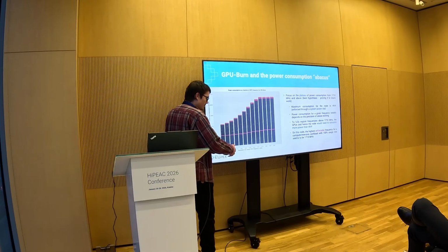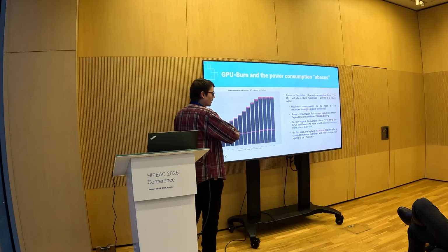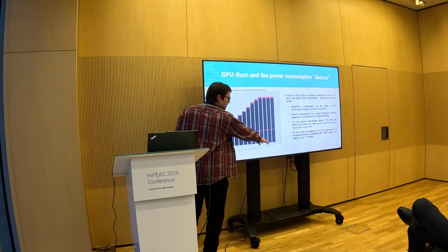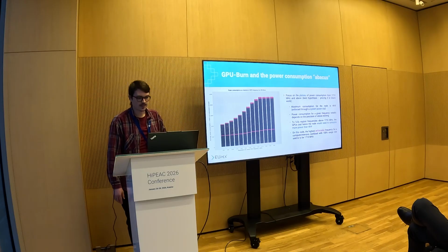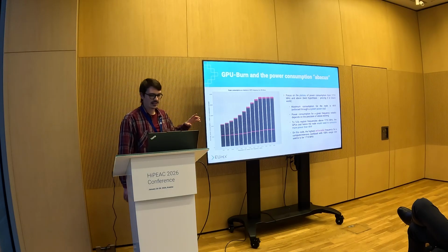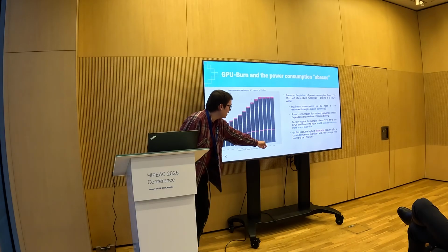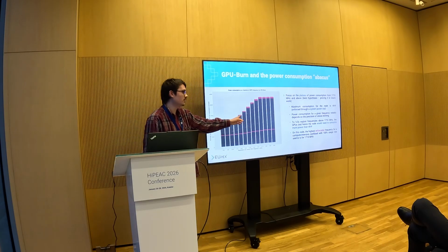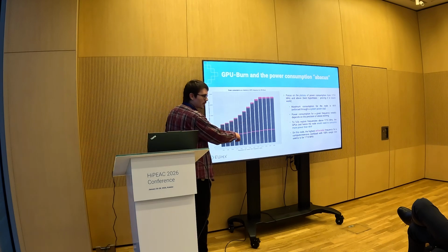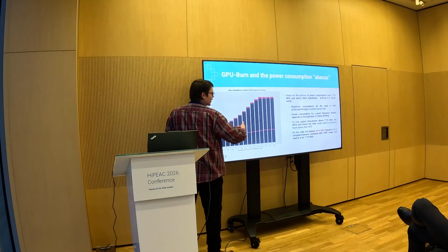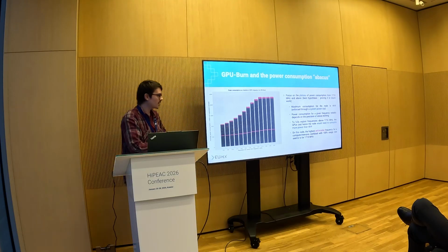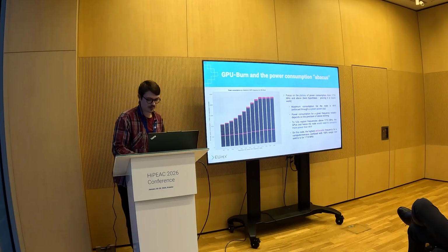So basically, it means that effectively, the node cannot sustain a higher frequency than 1710 MHz when fully loaded on this precise node. And something I want to have a few words about is that this value will depend on the specific node, because each GPU, depending on its etching, will not have the same power consumption for a given frequency. So you can have nodes which are better to reach higher frequencies and others which are not. And that's something to keep in mind, and there are lots of interesting discussions about that we can have off the presentation if you want.